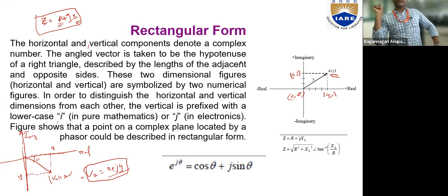Now when it comes to DC, the impedance offered, or the opposition offered to the flow of DC current, is only the resistance. But when it comes to AC, it also involves both inductor and capacitor, and the properties of inductors for AC and DC will definitely change. That is, the inductor opposes sudden changes in current in an AC system, whereas the capacitor doesn't allow sudden changes in voltage in an AC system. So they have a certain impact on the flow of current.